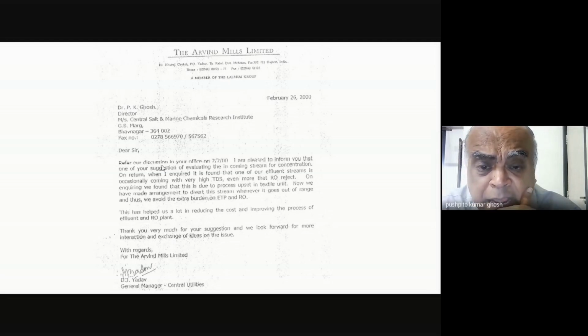They did that, and in fact, they told me that they were saving something like 30 lakhs a month, and I'm talking about 2000. So I don't know what it would be now, and I'll just read it out so that you understand. Refer our discussion in your office on 2nd February. I'm pleased to inform you that one of your suggestions of evaluating the incoming stream concentration was followed. When I inquired, it was found that one of our effluent streams is occasionally coming with very high TDS, even more than RO reject. On inquiring, we found that this is due to some process upset.